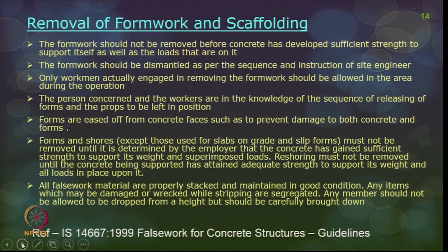So, all the falsework material is properly stacked, maintained, and sometimes quality checks are done, and then it is actually reused at the next levels. Any member should not be allowed to be dropped from a height and should be carefully brought down, because it may affect the strength of the formwork.